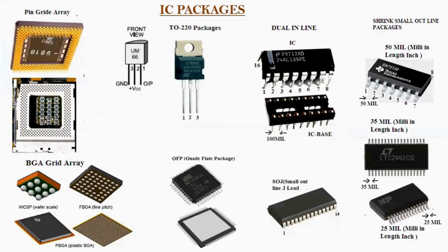That is called the IC package, right? Like in transistors, here also different packages will be there. What are packages actually? The packages are the shape, size, and number of pins. Like in transistors, we have studied 3-pin TO92 and TO220 packages.